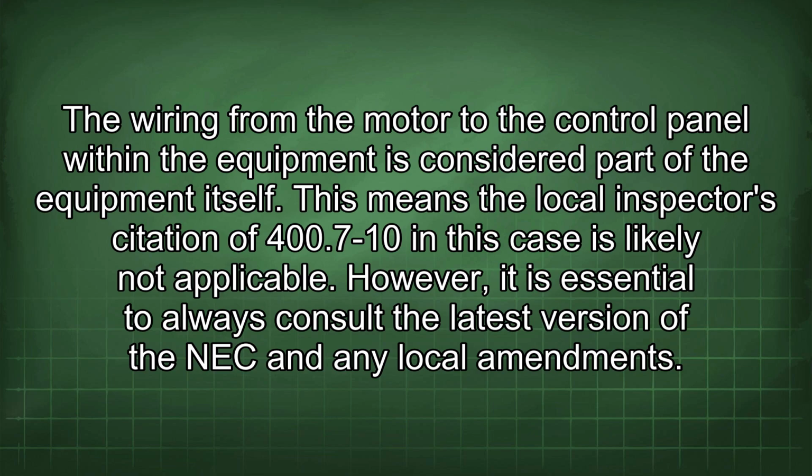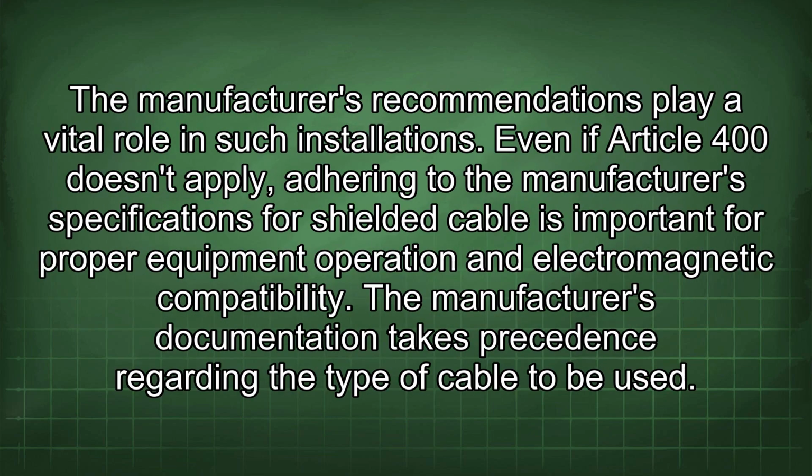However, it is essential to always consult the latest version of the NEC and any local amendments. The manufacturer's recommendations play a vital role in such installations. Even if Article 400 doesn't apply, adhering to the manufacturer's specifications for shielded cable is important for proper equipment operation and electromagnetic compatibility. The manufacturer's documentation takes precedence regarding the type of cable to be used.